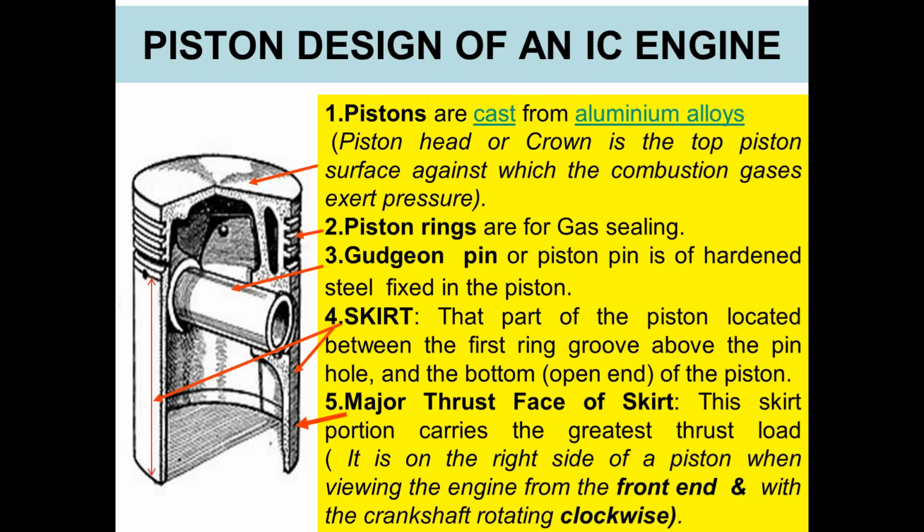Piston design of an IC engine. Pistons are cast from aluminum alloys. You see the piston head or crown is the top surface against which the combustion gases exert pressure. Piston rings are for gas sealing. The gudgeon pin or piston pin of hardened steel is fixed in the piston.